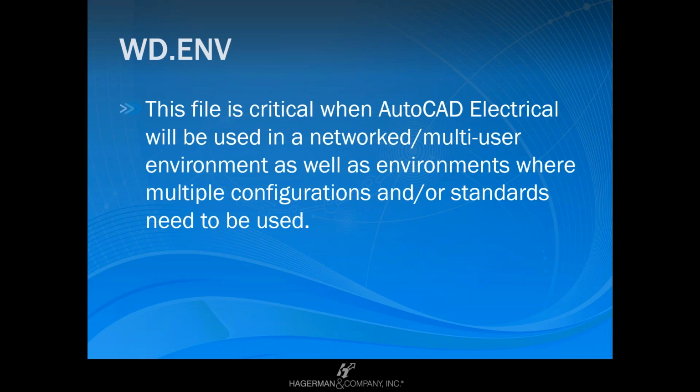Greg and I come from an OEM background where we had to work with a lot of different companies. And I'm just going to use automotive as an example. Ford had a very different standard than General Motors. So when we were doing projects for Ford, we had to do things like their title blocks, their specific symbols, their specific configurations that may not have worked for GM. Same thing with GM, we had to do very specific things for them. So that's where the environment file is, it's worth its weight in gold.